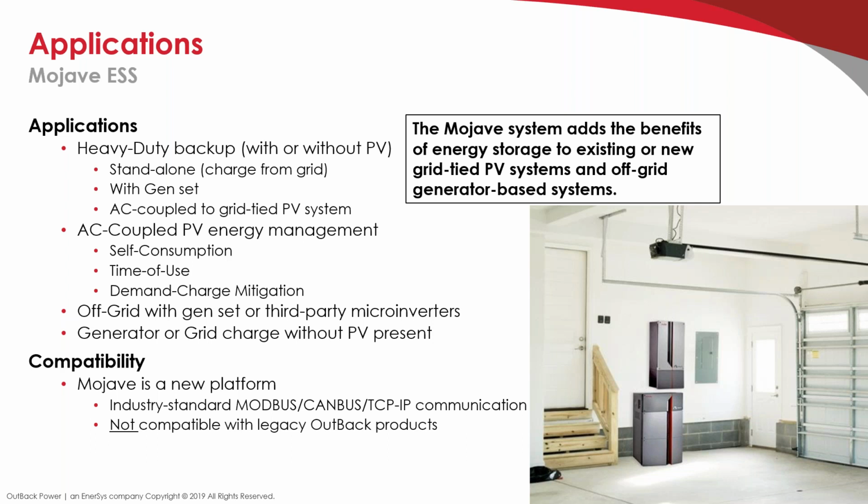So as I said before, we've updated the communications protocols, so there isn't any backwards compatibility. And to forestall a question I expect will come up, with the AC coupled unit, you will not be able to add a charge controller to it. We'll get to it a little bit later. We are working on a DC coupled variant, but for this unit, it's AC coupled, and that's what it does. There won't be any way to update it in the field until much later.